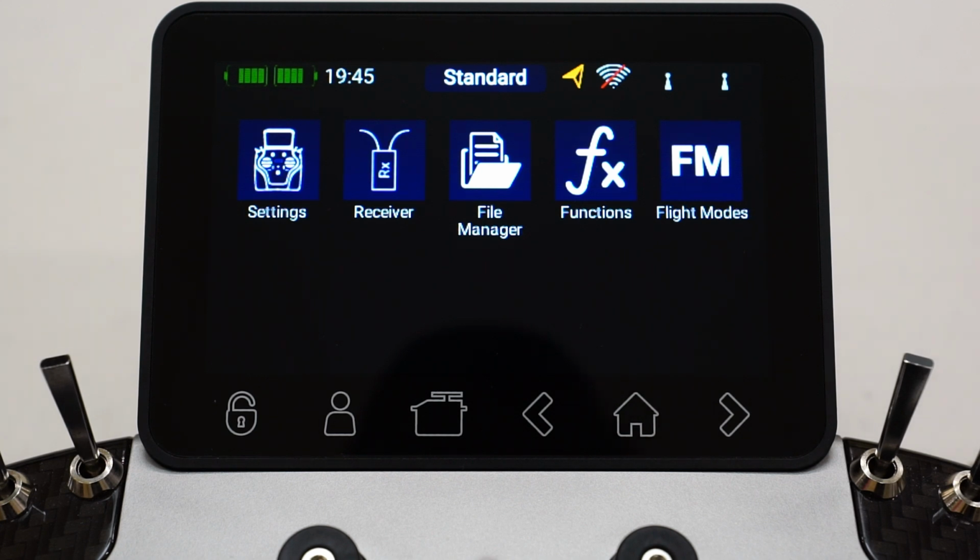Okay, so what do flight modes allow us to do? Okay, for instance, setups. I mentioned setups when I was talking about the helicopters. So for fixed-wing pilots, you're probably familiar with, say, dual rates. So typically in the old days, you'd have maybe 1 or 2 or 3 switches to activate your dual rates. So you might have one for your aileron, one for your elevator, one for your rudder. And you could flick in different rates for your flight surfaces. With flight modes, what that allows you to do is basically have one switch to activate, say, your 3 different rates or more if you want. So basically it's like having one trigger to activate a whole lot of different setups.